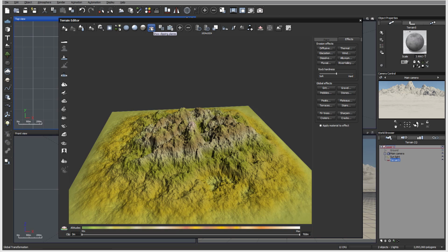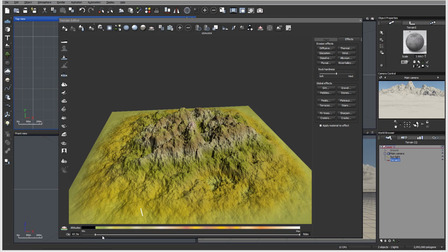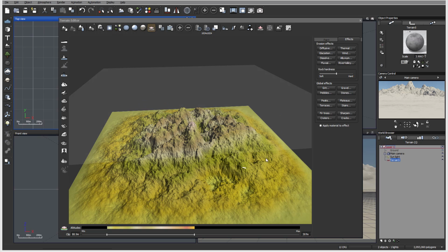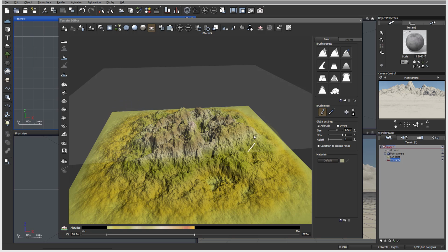We also have an option for showing the clipping plane. You notice when we created, I first created islands on the bottom, and we kind of cut them off by doing this. This allowed us to clip lower and higher altitude, like right here, but sometimes you cannot see it. By enabling this, we can see this clipping area.